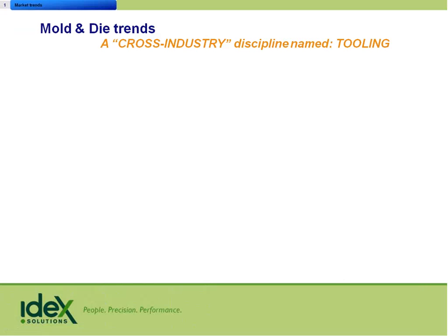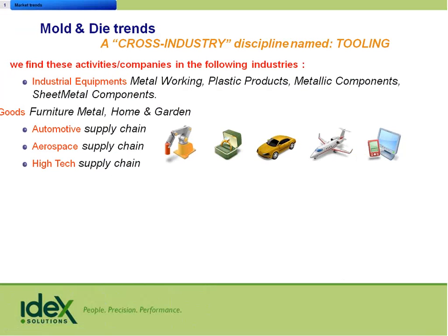In the past, people have used CATIA from a knowledgeware standpoint to build their own templates and to fit their specific needs. What mold tooling has done is it's captured a lot of the generic behaviors that customers were looking for and looking to build, generic templates. So it gives you a very, very strong starting point and gives you all these behaviors that work inside the tool that typically high-end users have to do themselves. So it allows you to do a design in context in a top-down design methodology without having any knowledge or idea what that really means. So it gives very base users high-end capabilities very easily.